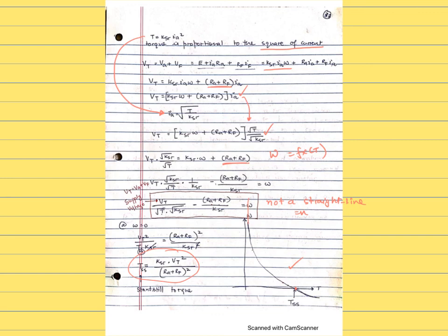So in case of a series motor, the standstill torque is very large. So it could be applied to applications where a large startup torque is required, like car engine starters. So at no load, we're coming closer to this end. The omega can be infinite, a very large speed, so that must be avoided. So a DC series motor should not run at no load. And it is important to have protection devices that remove the electrical power to a series motor when the load becomes disconnected.